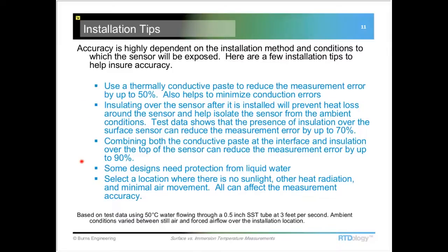And I did mention that some of these designs need to be protected from especially liquid water. Most of them are sealed up very well from just humidity that might be in the air. But liquid water is usually a little bit of a different story. It can seep its way past an epoxy seal that might be in a sensor, and you really need to further protect that sensor from liquid water.